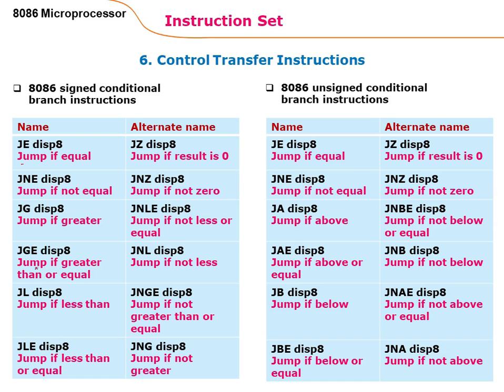Here the next instruction is JL, jump if less than, which is equivalent to jump if not greater or equal. JLE is nothing but jump if less than or equal. JNG is jump if not greater. So these two instructions are equivalent, and we can use these instructions depending upon the condition in the given problem statement or program. The unconditional sign branch instructions are also the same. So we can use these conditional and unconditional instructions to transfer the control to a particular memory location.